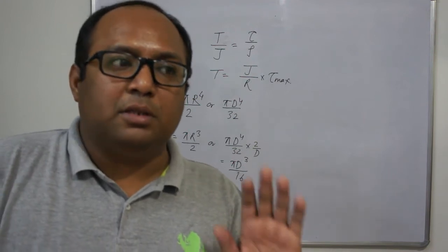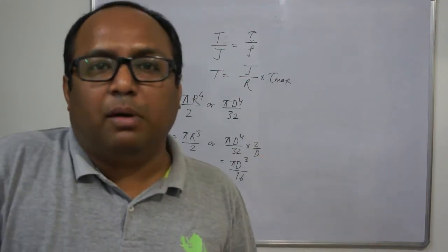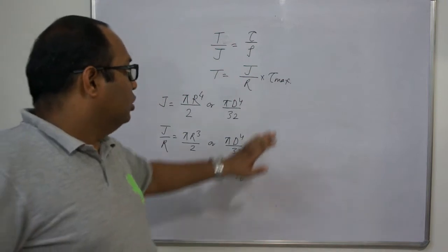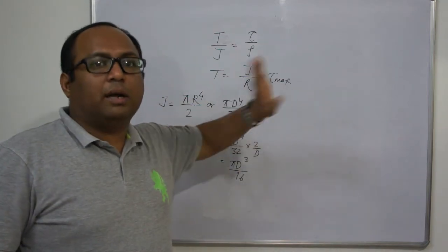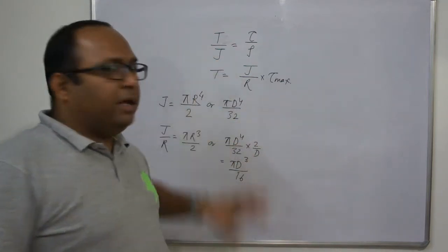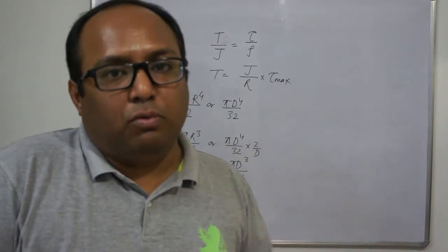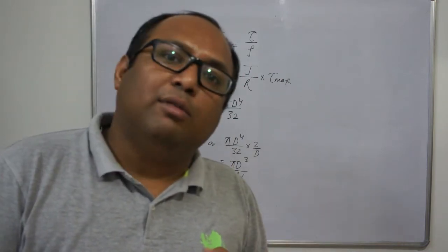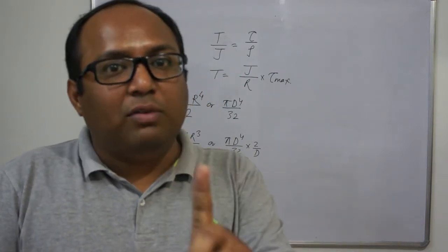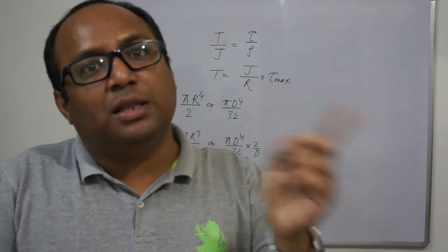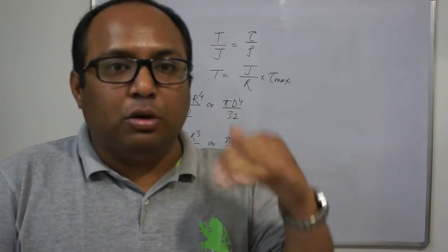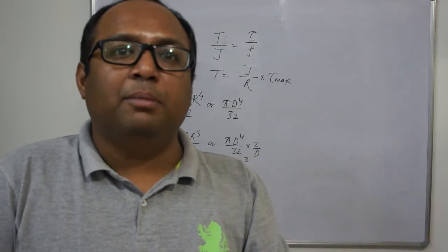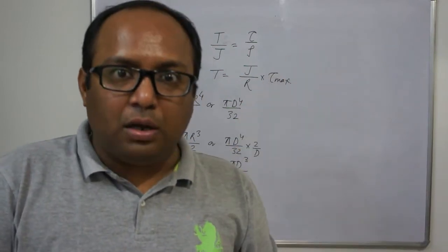It is the property, meaning the proportionality limit divided by the factor of safety. So you can get this from the data book, based on the amount of torque which you want to transfer. And how will you calculate the torque? The torque will be calculated from the power transmission and the RPM. So if you know the power transmission and the RPM, you can calculate the value of torque.